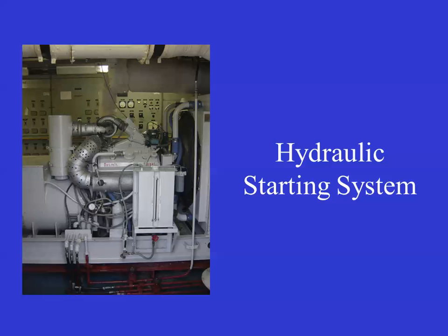And number two, if you drain the start air batteries for an emergency diesel generator, and you don't have any electric power on the ship, how are you going to charge the batteries back up and start the emergency? Where I have seen electric on merchant vessels for the emergency diesel generator, I have seen also an air start motor, so it literally has both. And then they'll have a small tank and a small air compressor.